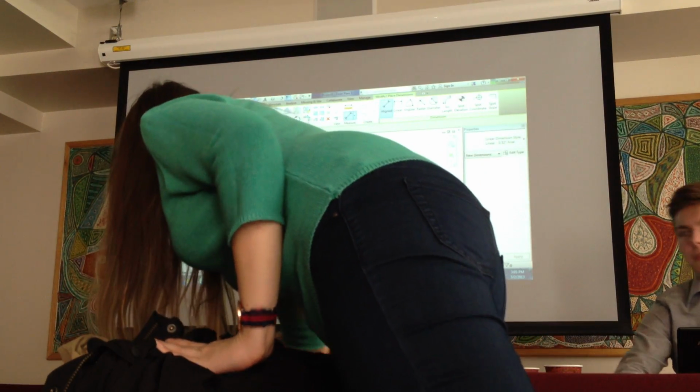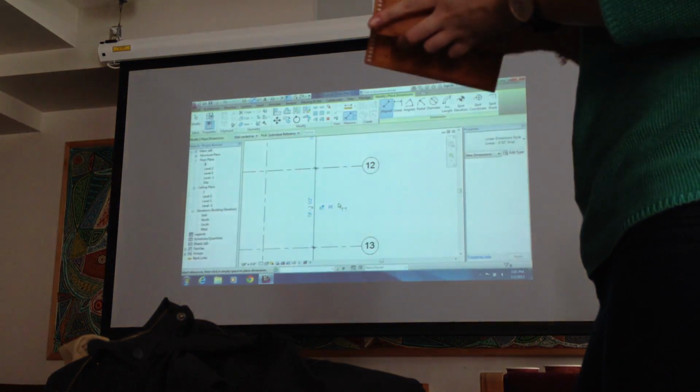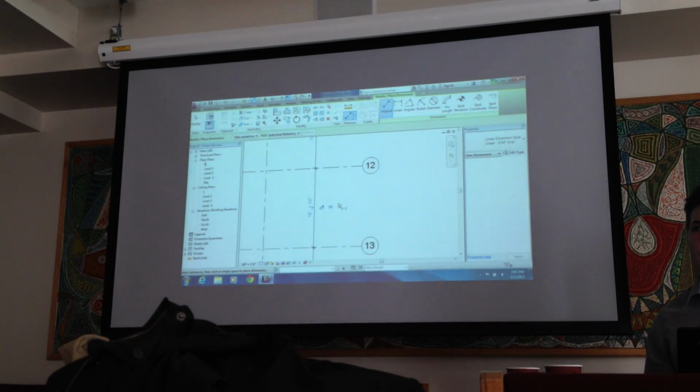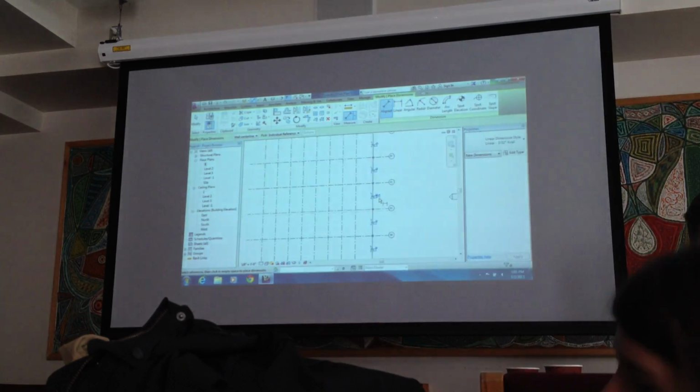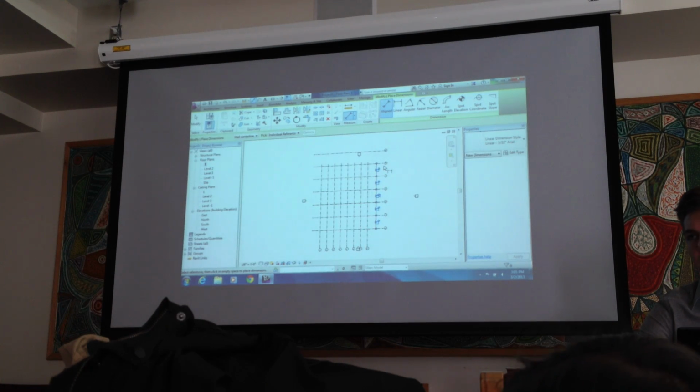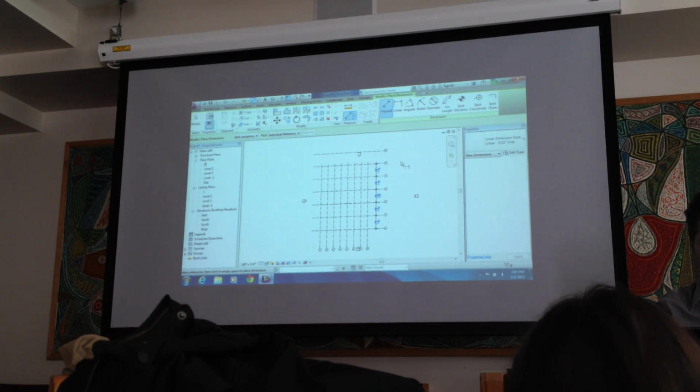And then you'll notice on the right hand side that small EQ button. So if you click it, it will automatically align all the grid lines together. So if you screwed up on a few of them, it will kind of fix it and make it right for you.